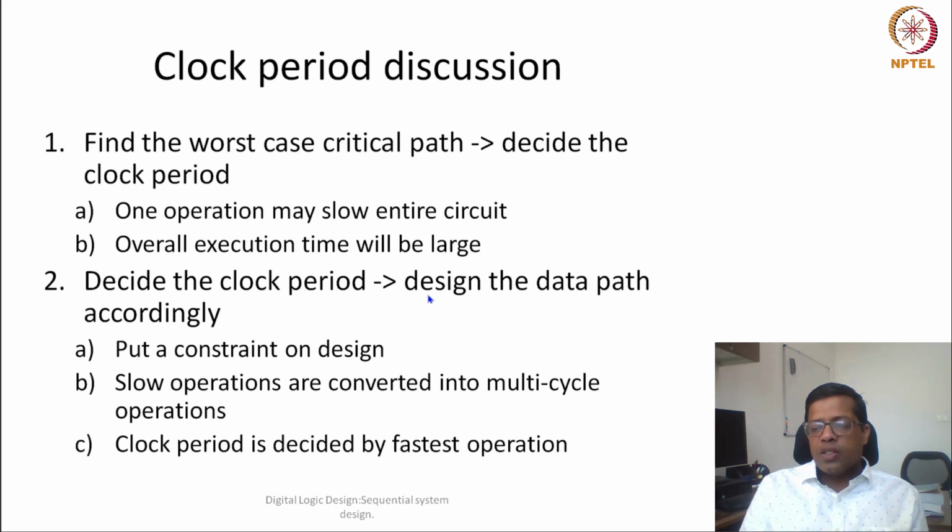And then you may still ask who is finally deciding what the clock period is. Although you are saying that it's a part of the specification, somebody would be deciding that specification, and there must be some rationale behind it. So usually the rationale is: what is the fastest operation, or what is the most common operation which is also quite fast, plus you add the register delay, you add the setup time of a register, and then you say that this is the clock period.